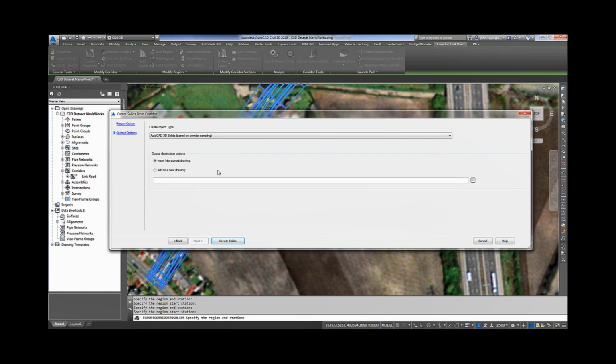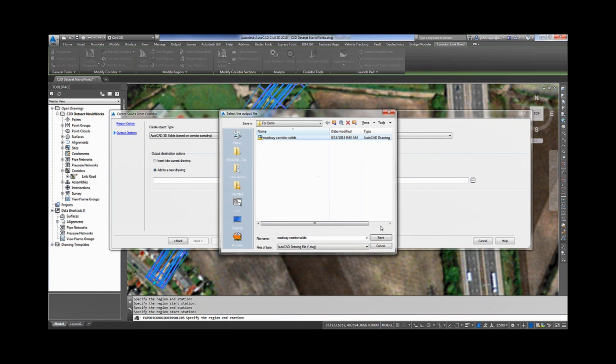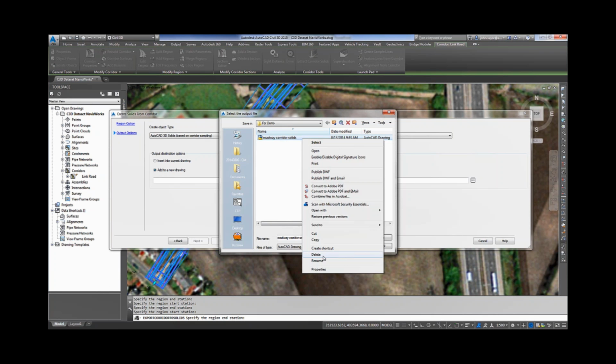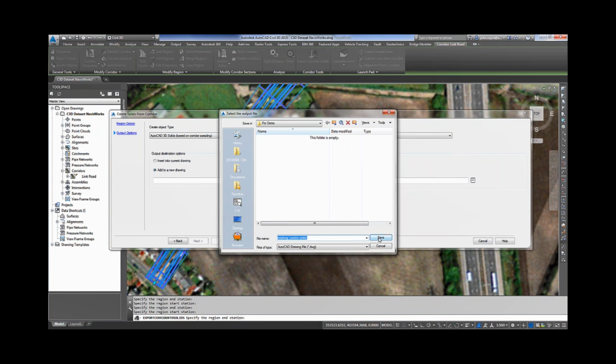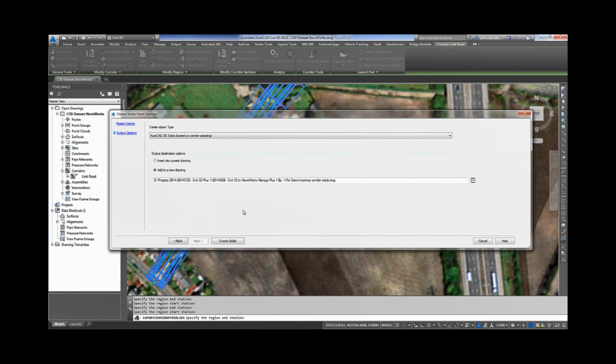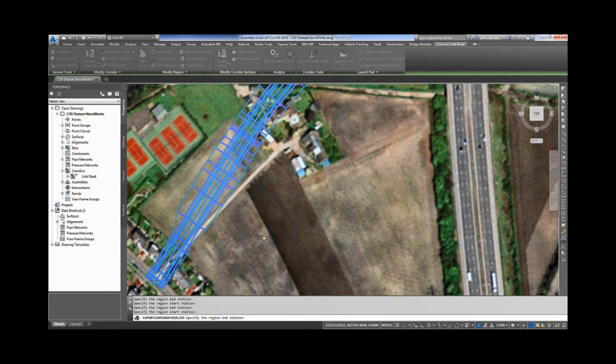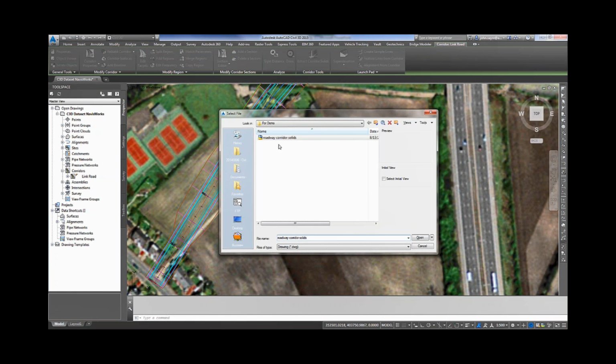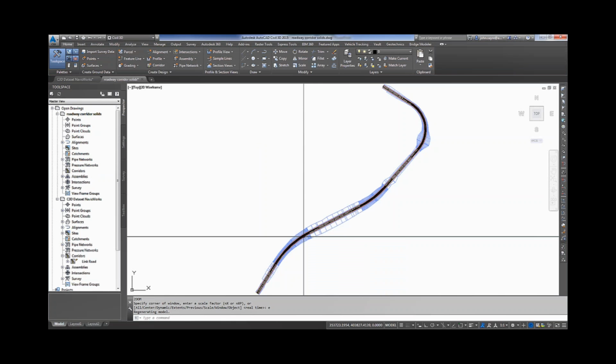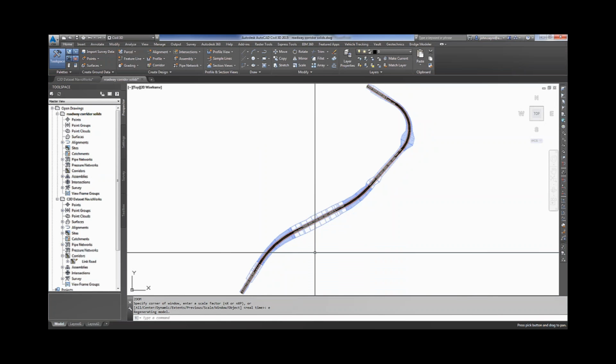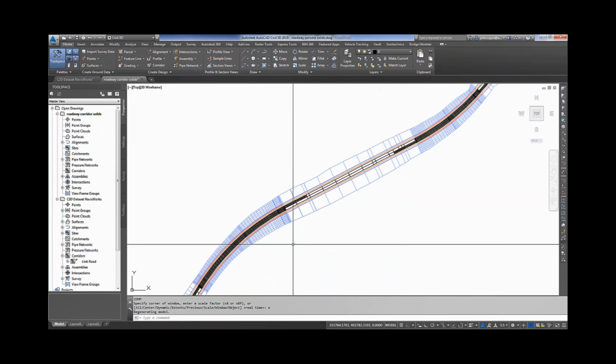So here what we were doing is we were breaking the road up into, I think it was like 100 meter or 300 meter increments, and we're now exporting out these solids so that it can be viewed and then timelined against within Navisworks. So obviously the critical thing here is that the attributes that are coming with it are all there, so that we can start to map the different elements to the Timeliner, and as you'll see as it steps through, you'll see the necessity there.